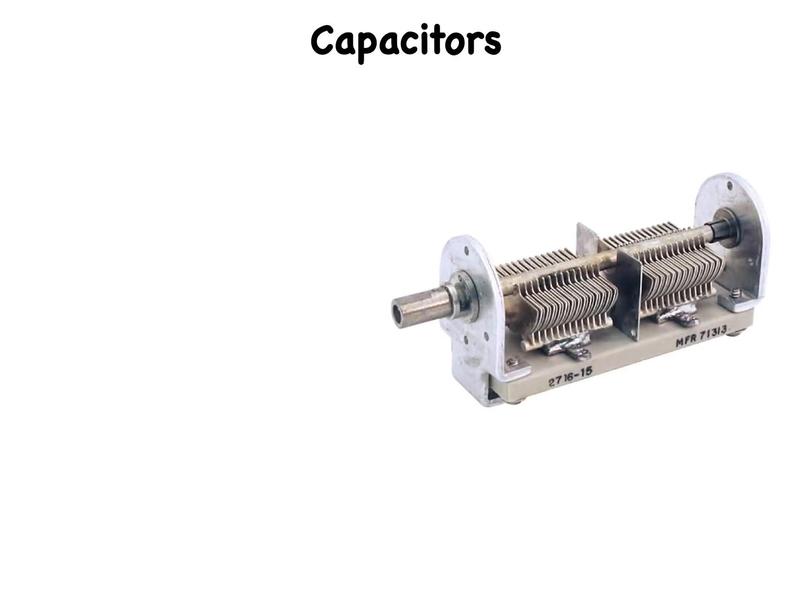An air variable capacitor, one with an air dielectric, can tune many types of radio frequency equipment including antenna matching networks, transmitter output circuits, and old-fashioned radios. A typical air variable capacitor has many interlaced plates, with the plates connected together alternately to form 2 distinct contact points. The set of plates that you can rotate is called the rotor. The set of plates that remain stationary is called the stator.